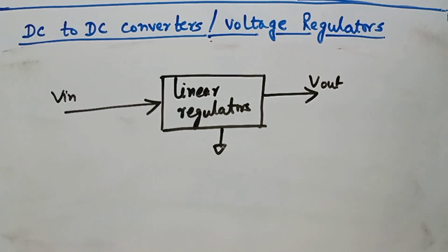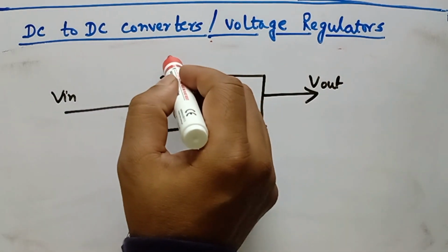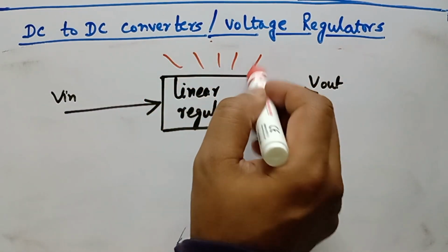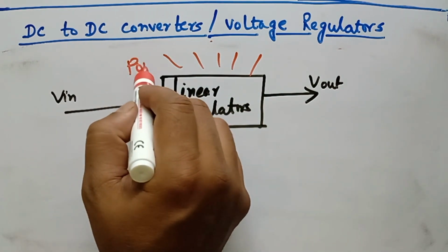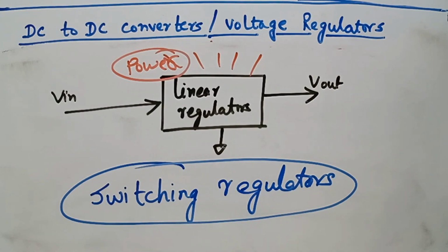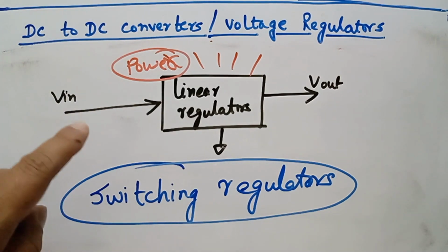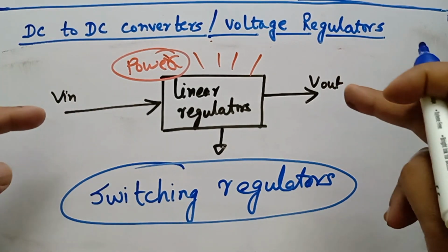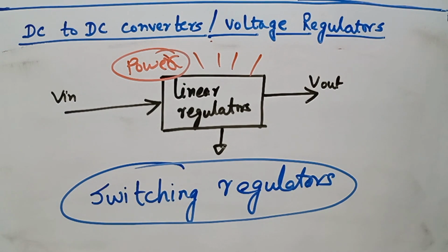As we have seen, with the linear regulators everything is very nice, cheap, easy, but the trouble is power dissipation. So what is the solution? The solution is switching regulators. These dissipate less power even at a huge drop across Vin and Vout for higher current values. But they're a little bit complex to design. Let us now discuss switching regulators' operation and functionality.